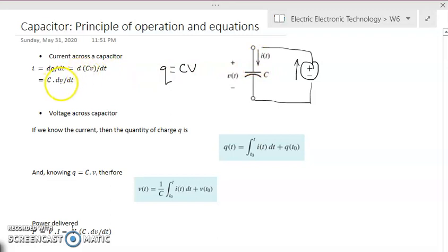But what happens when dV over dt becomes 0? It means the voltage across the capacitor is now equal to the voltage of the power supply. If it is equal, then dV over dt is 0, so you will have no current circulating. So once it is completely charged, the current will stop circulating. So that explains this equation of current, right? So I equals C dV over dt.